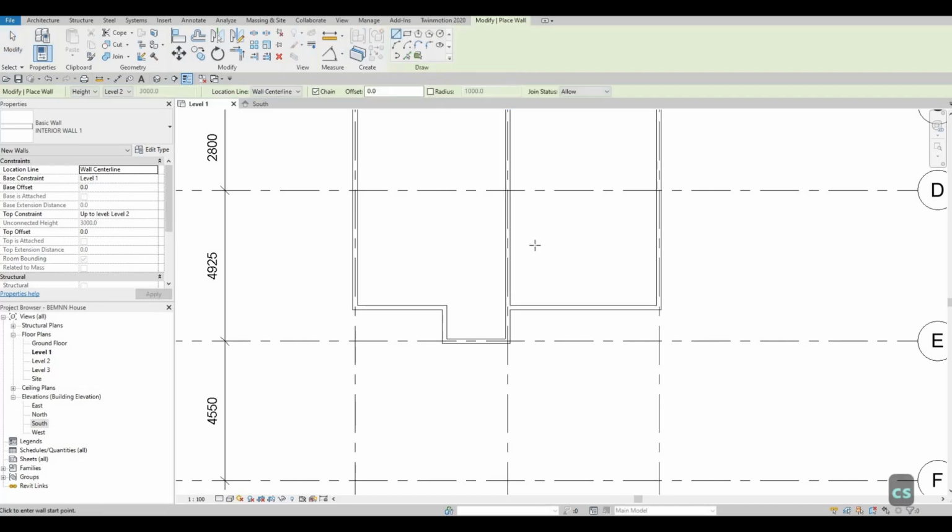We're gonna use CS, create similar, and we could add an interior wall right again. So here I'm going to add a wall first, all the way right here. As you can see, we have a temporary dimension here. You can select that, and then here we can type in 1950. So now we have our walls right here.